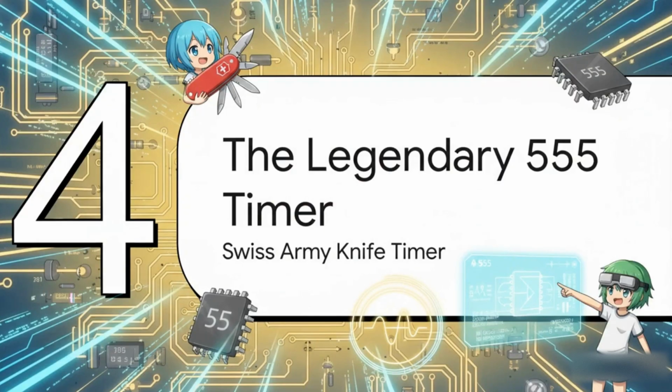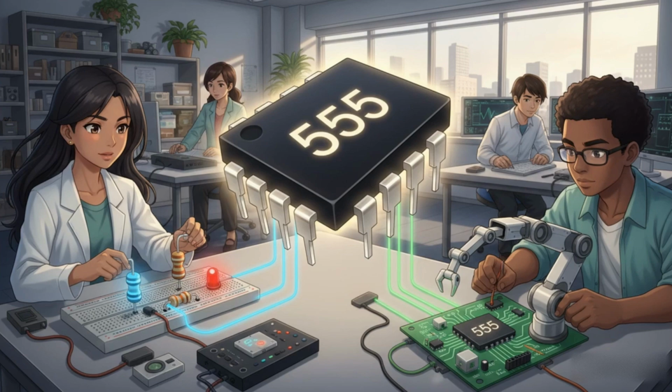Okay, so all of this theory about multivibrators, it all leads us to one of the most iconic, most beloved components in all of electronics. I want you to imagine taking all these fundamental building blocks and packing them into a single, dirt-cheap, and incredibly versatile little chip. Well, that chip exists, and it's the legendary 555 timer. And look, the 555 is famous for a reason. It's a pre-packaged powerhouse. Inside this tiny little chip, you've got all the essentials: the comparators, the flip-flop, the whole shebang. All you have to do is hook up a couple of resistors and a capacitor on the outside, and boom, you can make it an astable oscillator or a monostable timer. It really is the Swiss Army knife of timing circuits.